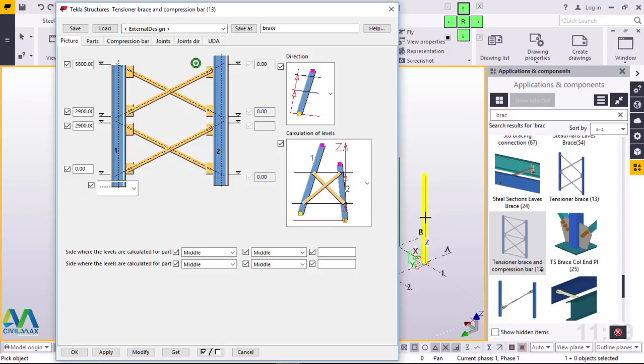The height of my column was 6 meters, so on top of this, instead of fitting 6 here on this macro, I gave it an offset of 200 millimeters off the connection on top here, because I will be populating these columns going upward to a height of 18 meters, so I didn't want this connection to clash with this connection on top here.